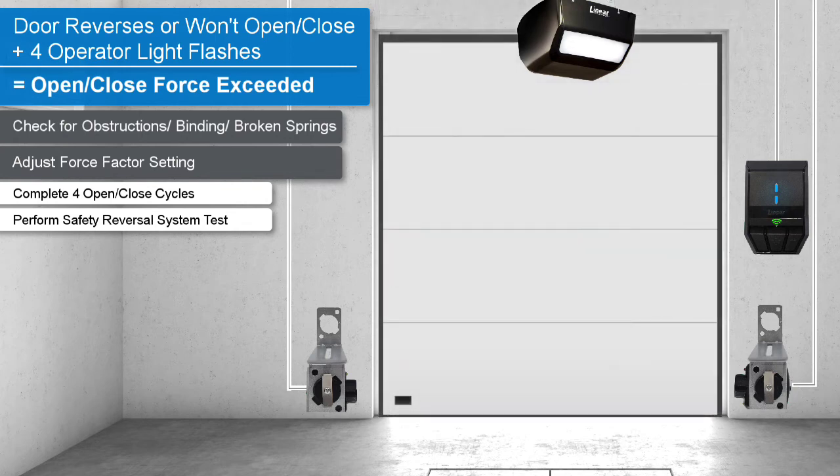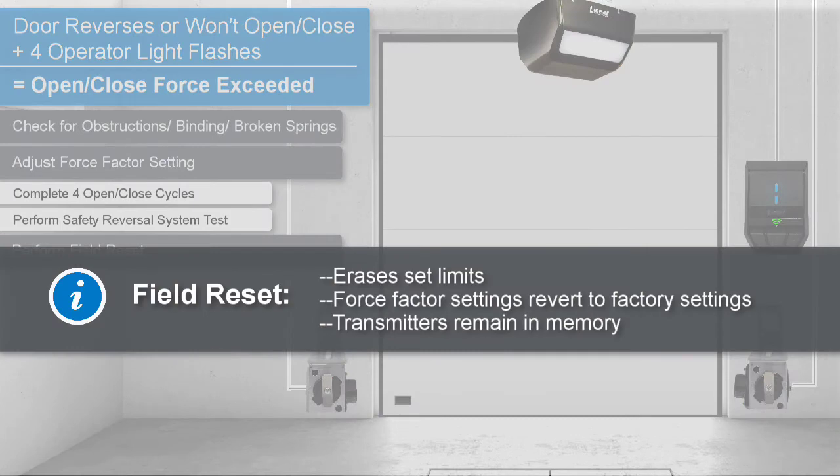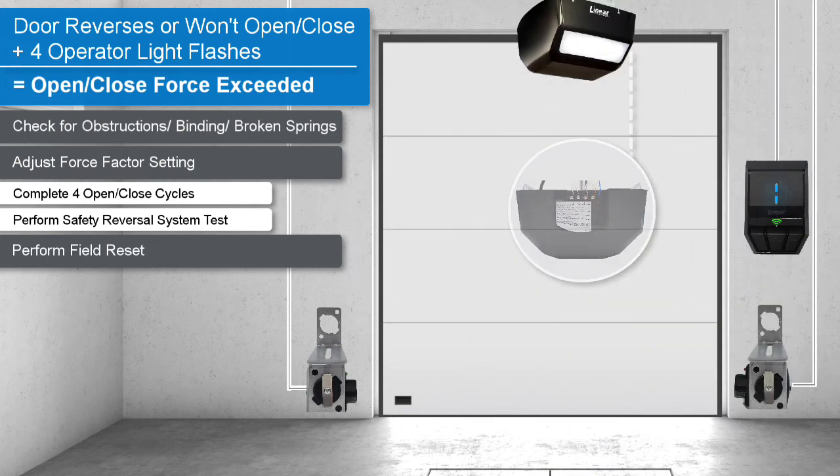If none of these steps resolves the issue, you can perform a field reset as a last resort. A field reset will erase all set limits and restore the force factor to its original factory settings. However, all programmed transmitters will remain in memory. To perform a field reset, press and hold the up, down, and learn buttons at the same time for 10 seconds. The operator light and red and green indicators will flash twice. Release the buttons. As mentioned earlier, the operator will reset force settings and erase all set limits, but will still keep all programmed transmitters in memory.